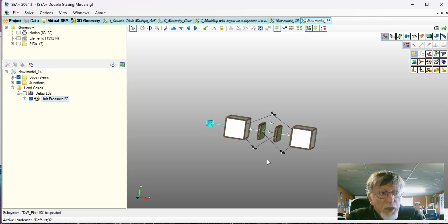To conclude, our model is working quite efficiently, gives very accurate data compared to test, and explains how the system is behaving. So we know now if the system is mass dominated, we have to change the mass, or damping dominated. And it's the beauty of statistical energy analysis.